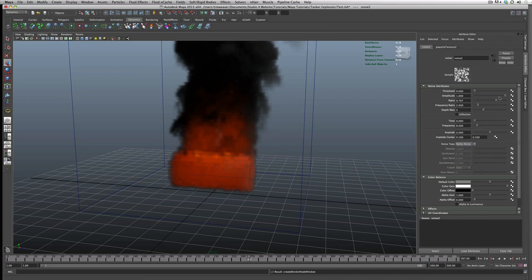And let's increase the frequency here, so we zoom in. And we really want this to be contrasted, so this needs to go up to maybe a value of 4. There we go. The more zoomed in, the better. You want more contrast, so Maya can really extrapolate where to emit the fluid effect and where not.